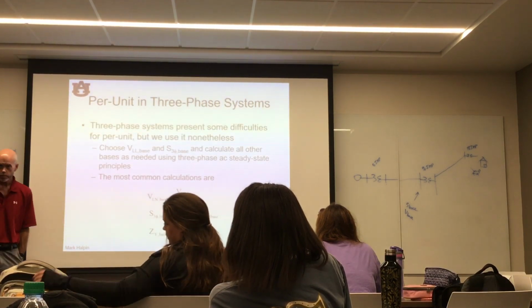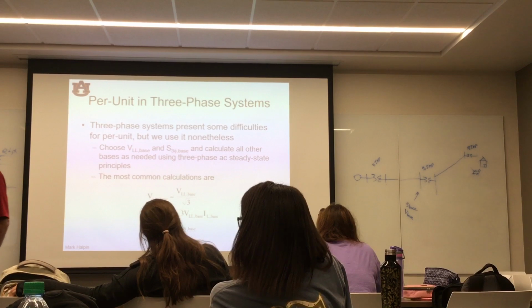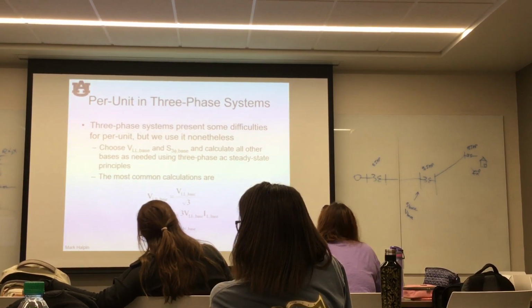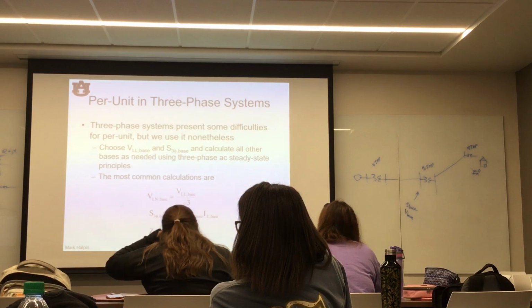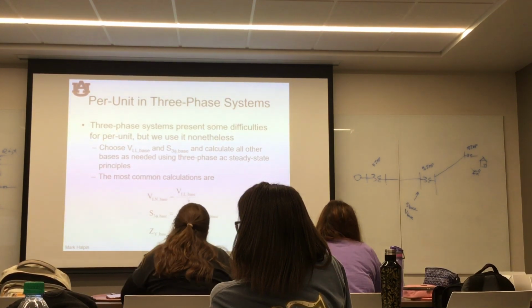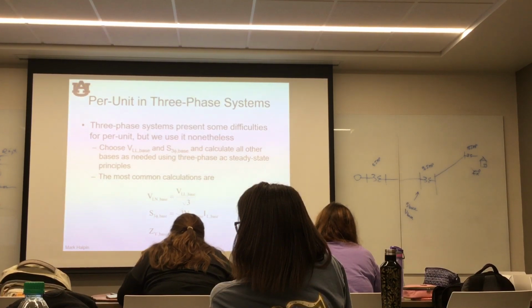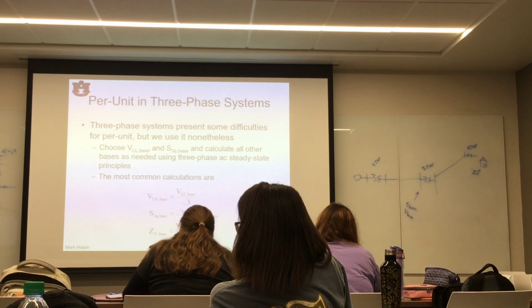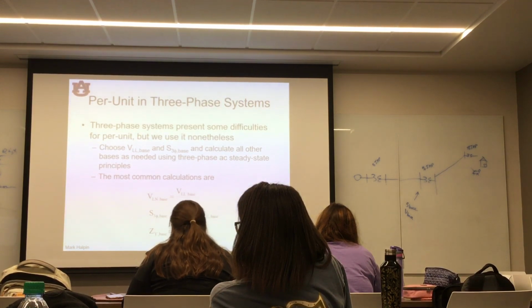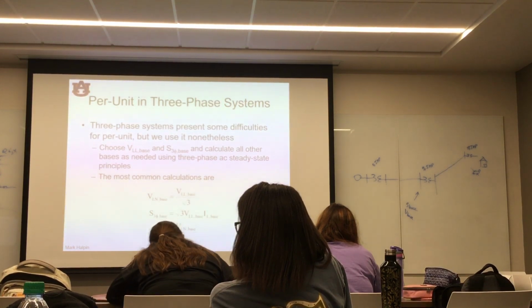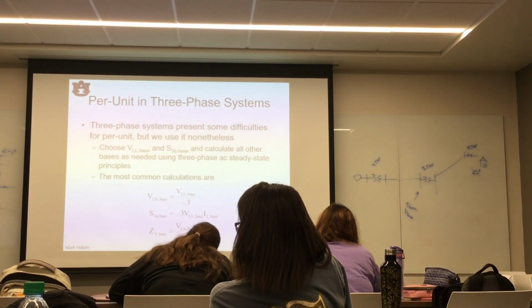All right? Okay. So, all that we've talked about has been for what you might call single phase or per phase. What about three phase? Well, now there are a lot of ways you can choose in three phase, but the basic premise remains. I can pick two bases, and two bases only. We customarily pick a power base and a voltage base.